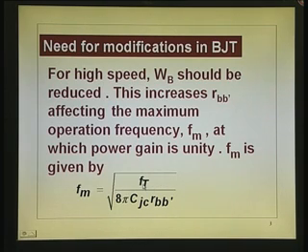You can improve the cutoff frequency by reducing the base width. But the maximum operation frequency where power gain is unity is limited by Ft and also CJC, the collector junction capacitance. You can reduce it, and if I have an n minus layer on the collector, automatically the depletion layer width becomes longer and the CJC becomes smaller. RBB dash, the RC combination between the collector base capacitance and the base spreading resistance together bring down the maximum operating frequency. This is a general formula, I just borrowed it straight away, there is no point in spending time deriving it from the equivalent circuit. So, it hits the frequency of operation finally.